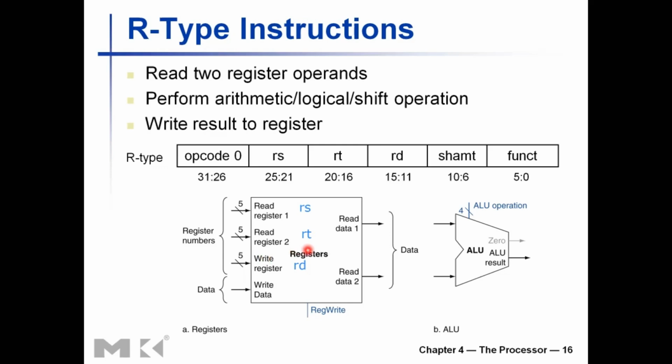Okay. Then when you provide the 2 read addresses, RS and RT, the corresponding values can be taken from the 2 read data ports, read data 1 and read data 2. And those data should be forwarded into the ALU as operands, first operand, second operand. So these are 32-bit numbers that we are getting from here, because the register file has 32-bit registers. So you are getting a 32-bit value as the first operand into the ALU and a 32-bit value as a second operand into the ALU.